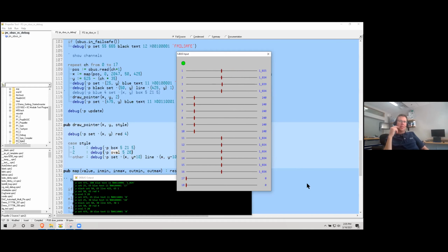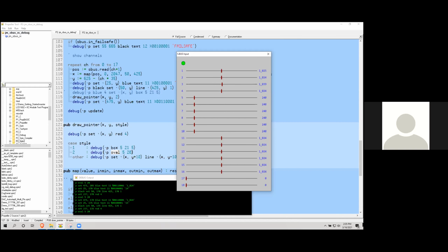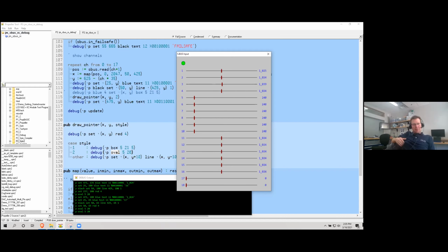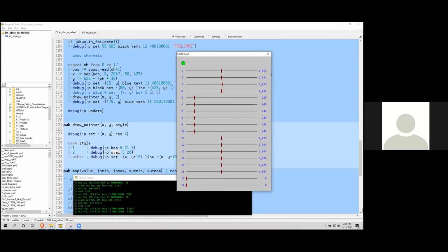John, I couldn't find the 18 channel version of that. So before you sign off today, get us a link, because we're all wondering what you're really using. Oh no, so Ken, here's the thing. I don't know that Skyfly has an 18 channel. The sbus protocol supports 18 channels, and the receiver is in fact putting out 18 channels, but since it's only a 10 channel device, you see it puts these channels at center and the digital channels at off.